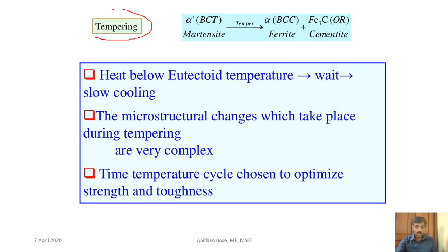Now tempering is a very important process that is done after martensite transformation has occurred. So suppose we want to make a material very strong, so general tendency is what? We first austenize the steel, and then we quench it. That means water quenching. By water quenching we form martensite, but that martensite is very brittle and not suitable for different machine components or different parts, structural parts, and that is why some amount of ductility is required to be imparted so that they become tough.